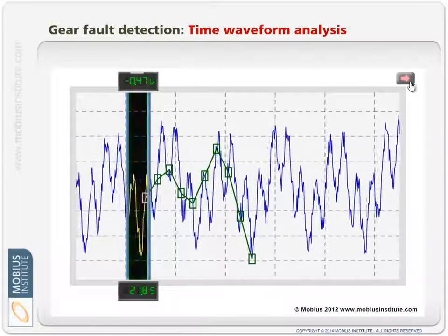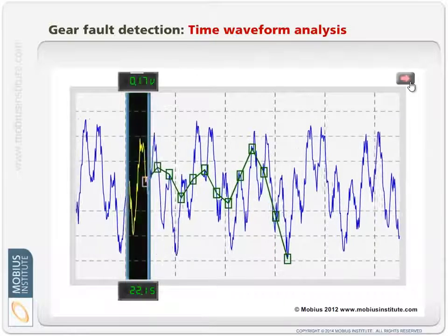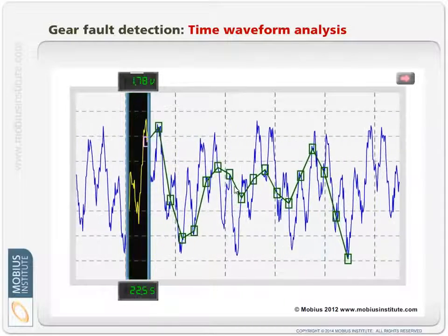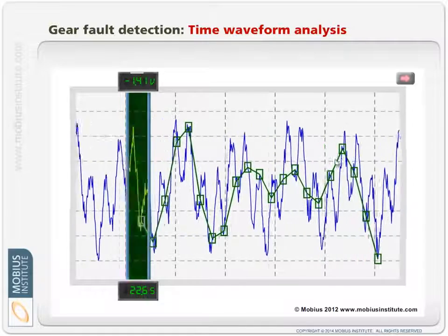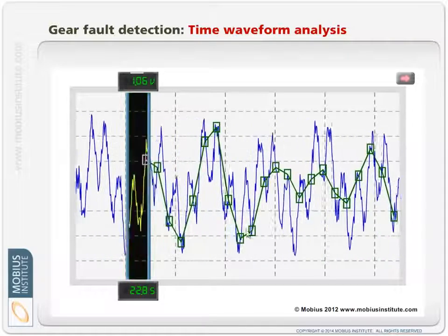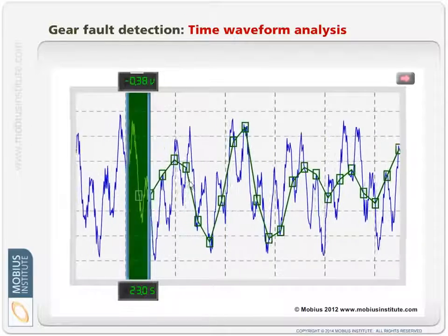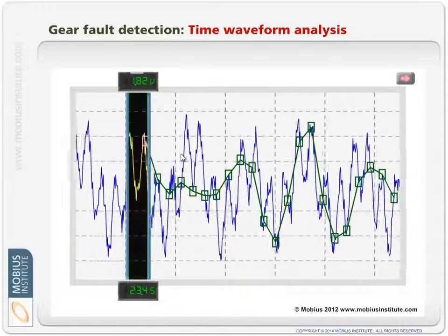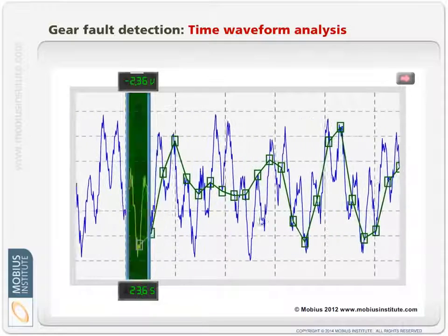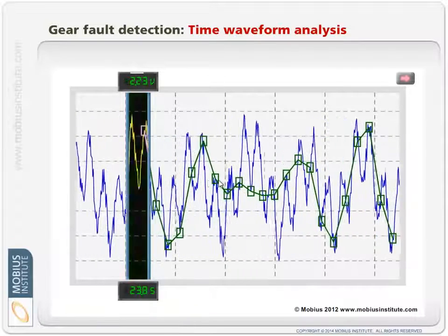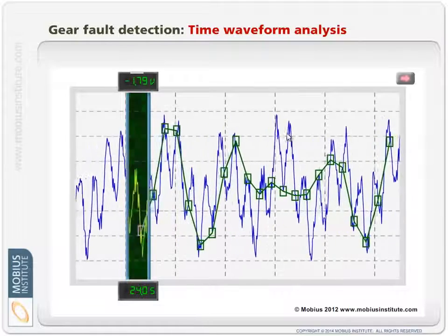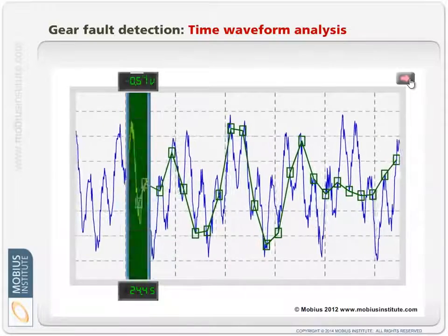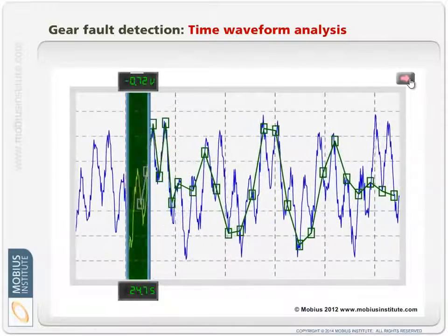But if the sample time, the time between each one of these samples, is too slow, you can see that the waveform, this green trace here, is what the analyzer will remember and then put through the FFT and display to you in a time waveform window. Well, this green trace has nothing to do with the real vibration, does it? It's obviously poor. We are obviously sampling too slowly. So we speed up the sample rate, the number of samples per second.